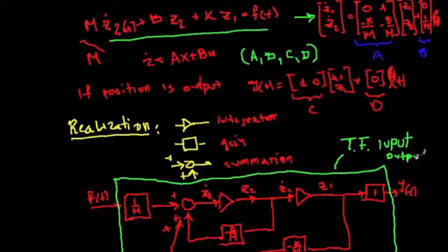In other words, if we realize the modeling of this system by these electrical engineering elements, which are just a summation, simple gain, and integration, we can design the relationship between a force and the position in this mechanical system. Therefore, we conceptually presented state space modeling from the first principle equations of mechanics, and when we do the realization with the integrator, gain and summation, we obtain something that is an input-output or transfer function system representation.